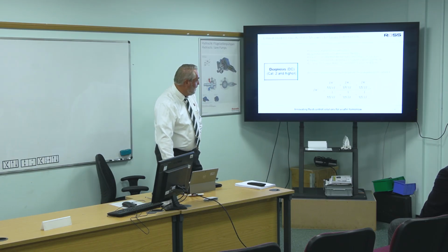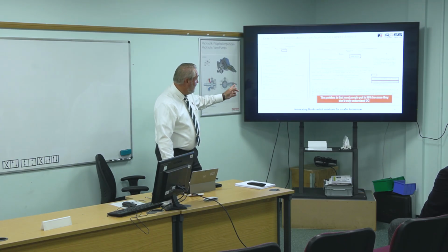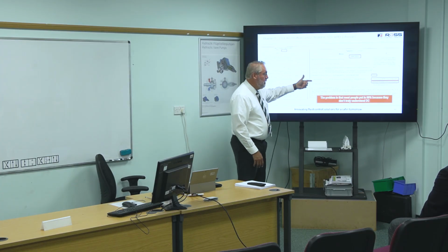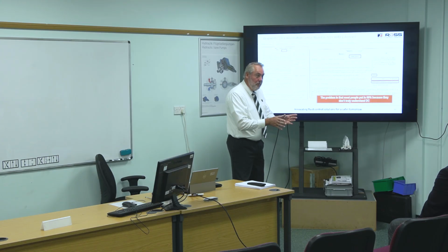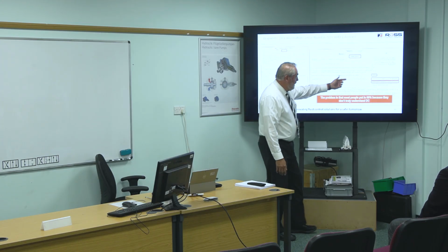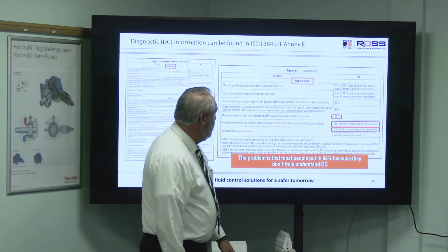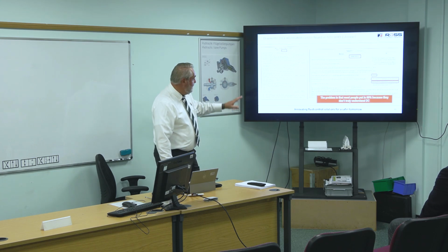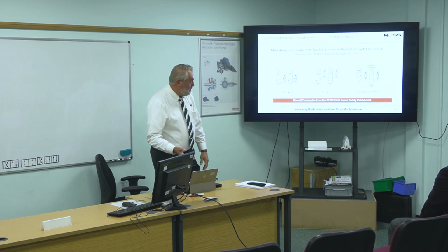Well, guess what? We're going to use that same MTTFD information along with something called diagnostic coverage, and that basically depends on where you're putting your monitoring switches. Remember, you and I were talking about pressure switches. Depending on where you put it, you could claim anywhere from 0 to 99. And so looking at your circuits and choosing the correct diagnostic coverage then is important.